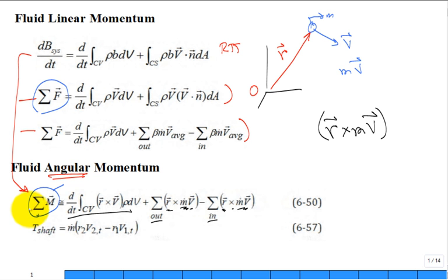Often it boils down to something very simple for some problems, but you don't want to boil it down too quick. Often we have a rotational system and we just apply a torque to a rotating shaft, and there you go. It's changing the fluid flow's angular momentum as it goes through a control volume. Well, this is all vector entities, and then we typically apply it to a system rotating in a plane, where I'm applying a torque to a shaft that's perpendicular to that plane. Right, so if there's any flow up.